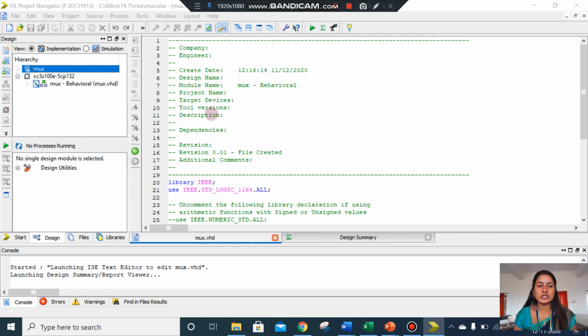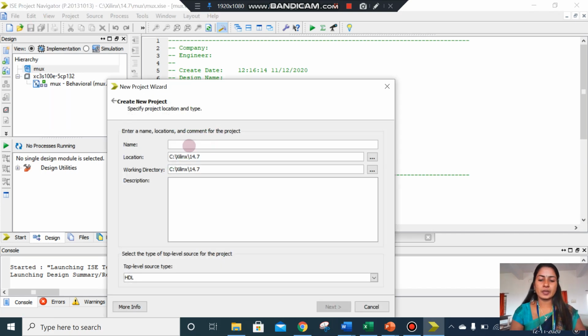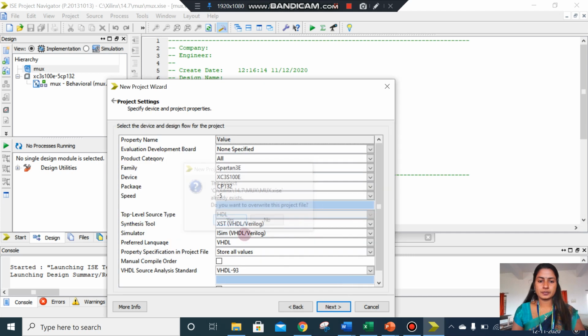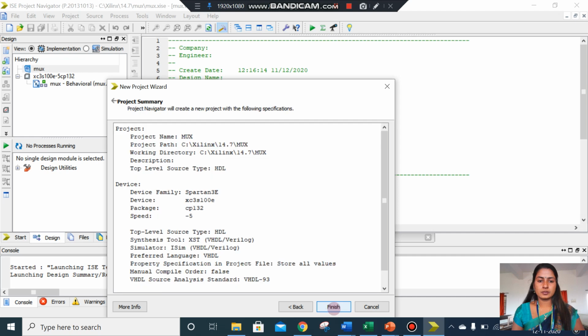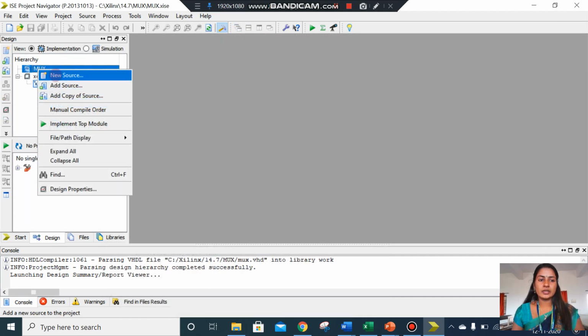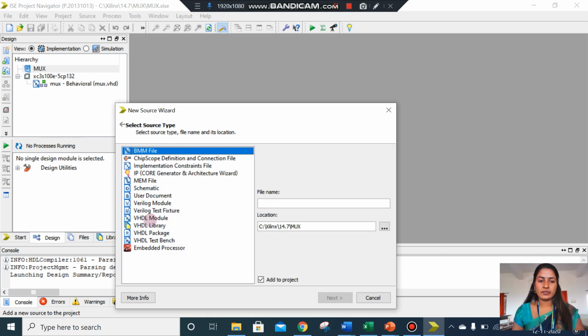I am taking a new project. I am giving the name mux. Finish. Okay, right click on that, new source, VHDL module, mux.